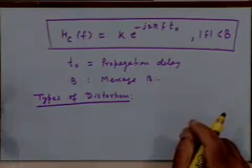Linear because they are arising from the non-ideal characteristics of a linear filter, right, which is being used to model the channel. The ideal characteristics are, it should be a linear filter, but besides linearity you want the magnitude transfer function to be constant. A linear filter may also have a magnitude transfer function which is not constant, right.